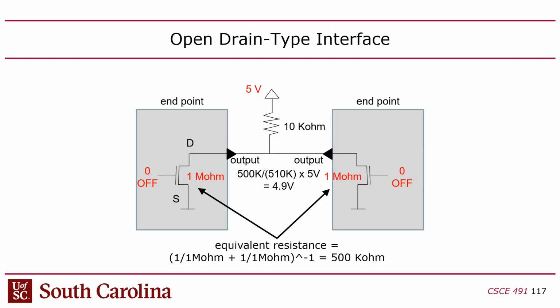And then the problem is just at that point, I just have a 10 kilohm resistor up to VDD. I'm going to start sinking current. I'm going to start sapping current from the power supply. But 10 kilohms is high enough that it's not a lot, it's like microamps, right? So that's not a real big deal. It's not as good as a push-pull in terms of efficiency, but it's still not a significant amount of current. So anyway, that's the idea.